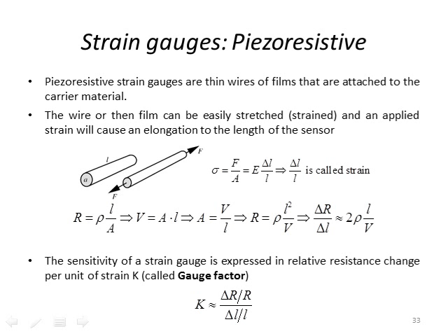Very simple concept: you have material and you're stretching it and you change the resistance, and then you want to turn that delta L over L into a delta R over R, and then we do the sensing, much like we did in lecture 3, where we were using a full bridge configuration with delta R plus and minus depending on how you strain the material.